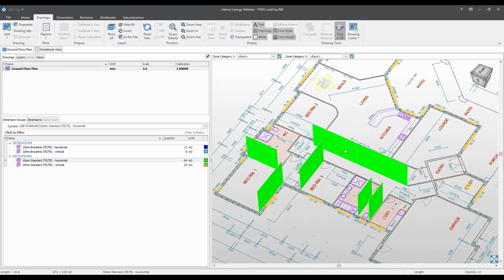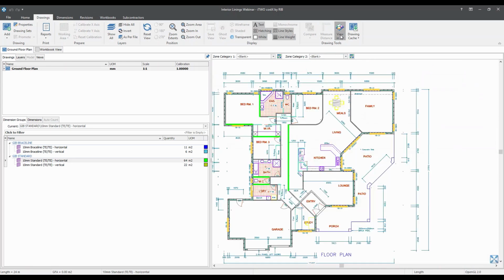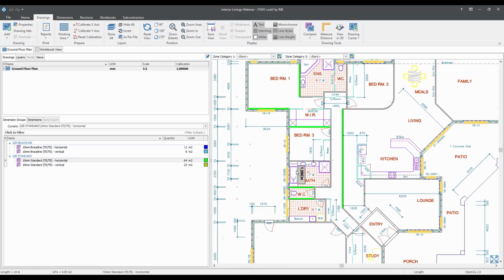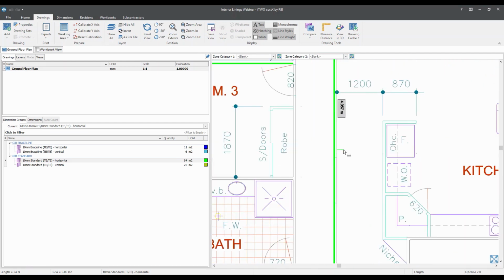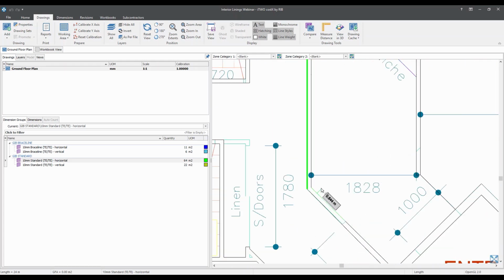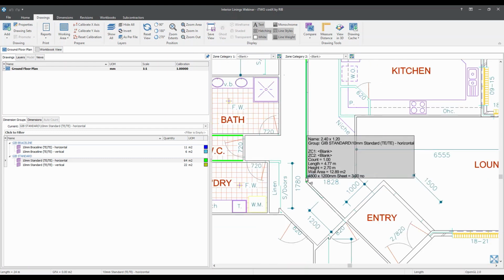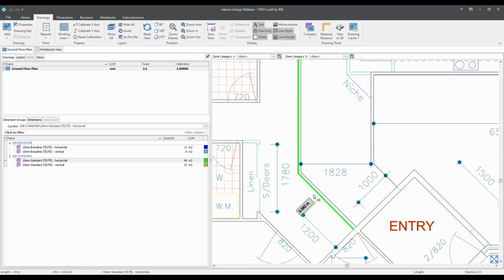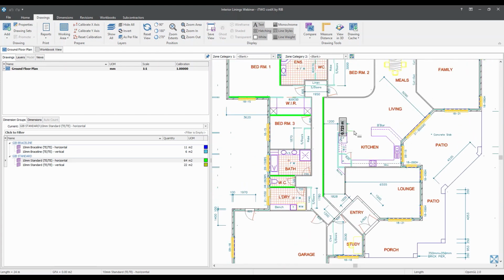So again, we can view that in 3D. So those are horizontally placed. Obviously we could check to see if they would fit vertically too, but I was just demonstrating this trim start functionality. In the same way you can trim the end. So if I wanted to do this and then trim this end part, I could press the close square bracket. So very useful with length in general when you're measuring doors, windows, and in this case partitions and walls.